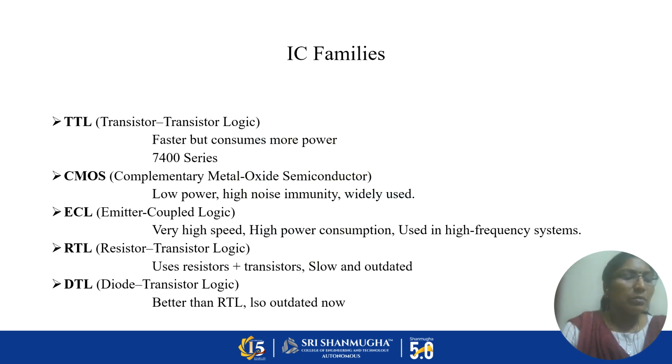And IC families, the families used in a chip. First one is TTL. TTL means transistor-transistor logic. Next one is CMOS, complementary metal oxide semiconductor. This CMOS family is the most used in the electronics field because this chip has low power and high noise immunity, and is widely used. Next one is ECL. ECL means emitter coupled logic, then RTL, resistor transistor logic, and finally DTL, diode transistor logic.